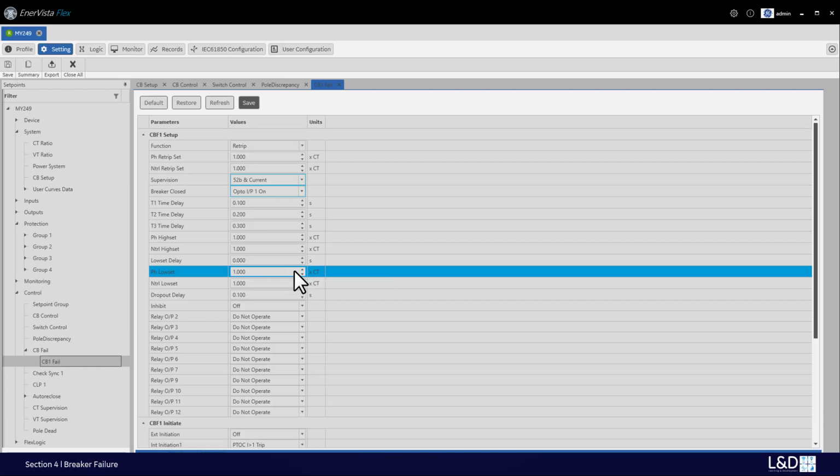For example, it can change from a current which flows before a breaker inserts a pre-insertion resistor (PIR) into the faulted circuit to a lower level after resistor insertion. The delay interval between high set and low set is the expected breaker opening time. Different breaker manufacturers have different designs of this PIR, so it is important to understand the sequence of the PIR operation during the opening before setting this parameter.